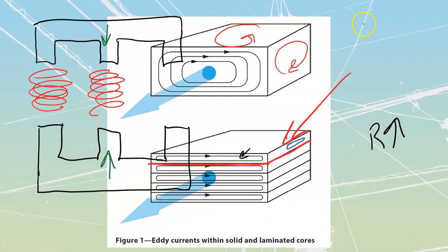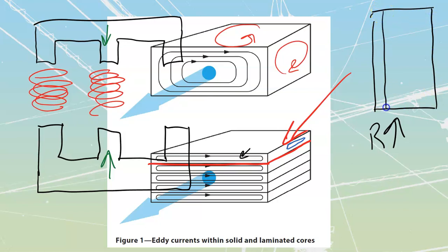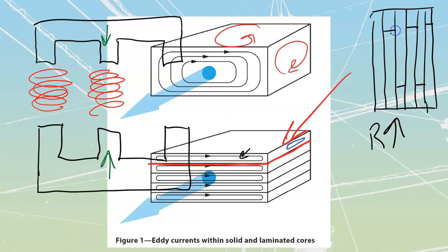If you take a look at the side view of a transformer, and I'll just make one that's made up of relatively few laminations, you're going to see that there are laminations that are oftentimes overlapped like this. That means that as they pull this thing apart, they would be able to pull those two sets of laminations apart. You're also usually going to see weld marks. That means that they have welded in a rod or something like that through here to hold these together.